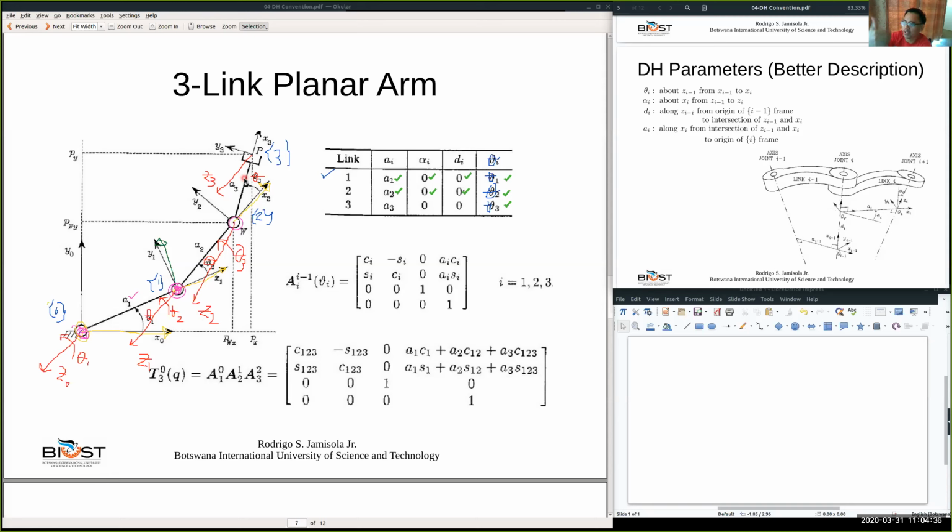So you rotate about X3. So X3 is that axis of rotation, and then you use it as the thumb direction. So your Z2 to Z3. So Z2 and Z3 are going in that direction out of the paper. There's no rotation because they are parallel. Both of them are parallel, Z2 and Z3, and so there's no rotation about X3. And so your alpha 3 is 0. So we're done. Alpha 3 is 0. Okay.